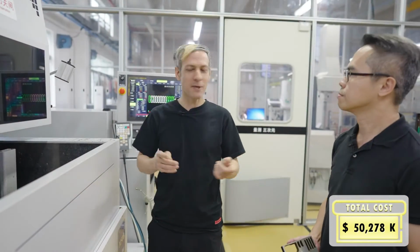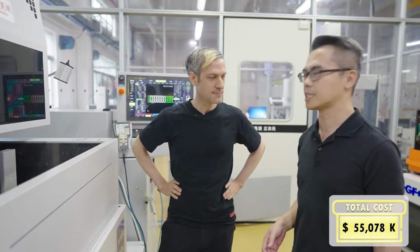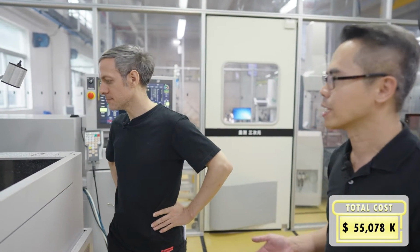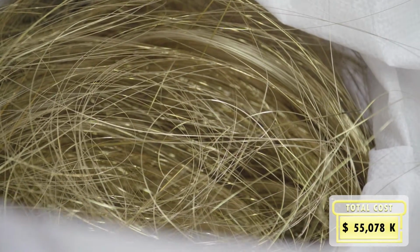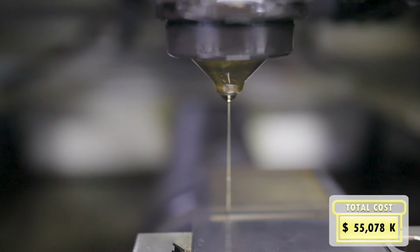Alex, can you explain how this machine is different from the other machines we just saw? The other machine that we just saw is the sinker EDM, but this one we call a wire EDM. What is wire EDM? We use very thin copper wire to cut into the steel, so that with this kind of machine, we can cut a very straight edge.